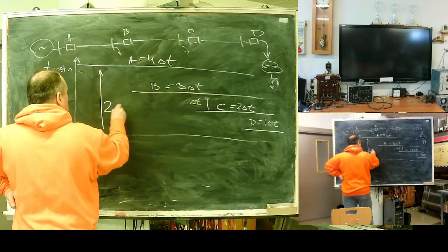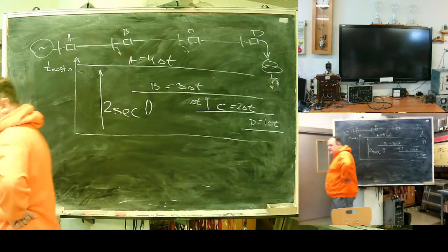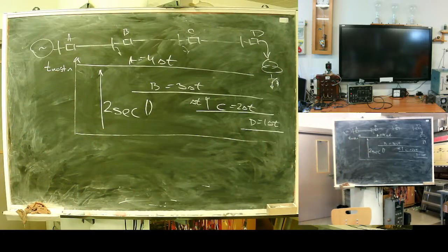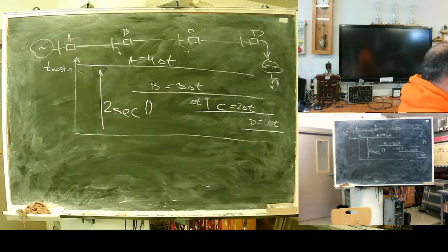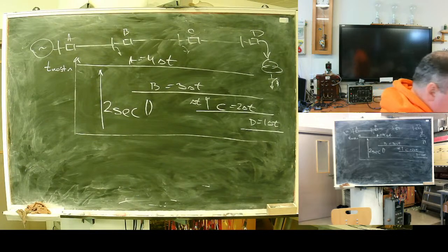This is 2 seconds of delay when the fault current is maximum, when the fault is at the beginning of your supply chain. When the delay is maximum. At the beginning. I don't think it's a very good idea.